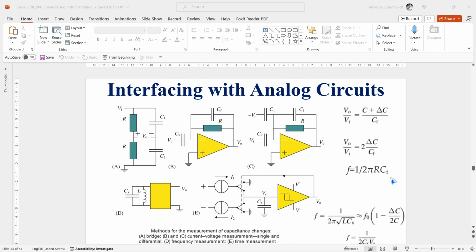The performance of the measurement is mainly limited by the phase difference between the two AC voltage sources. The output appears to be very sensitive to deviation from the required 180 degrees phase difference, a fact that can be used to create a sensitive capacitance to phase converter.